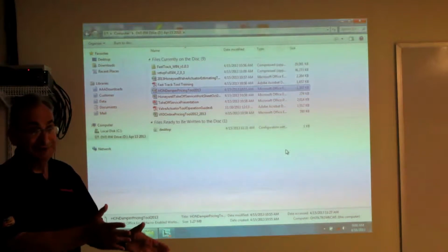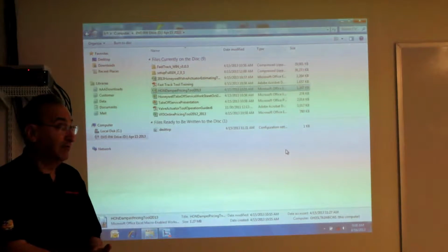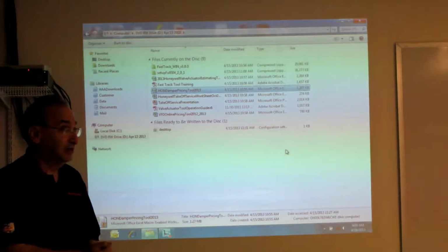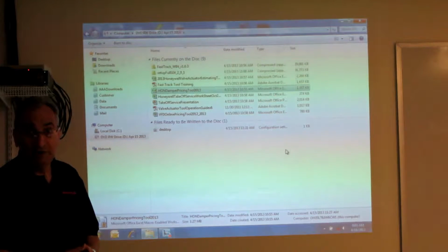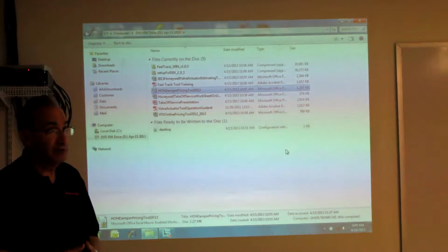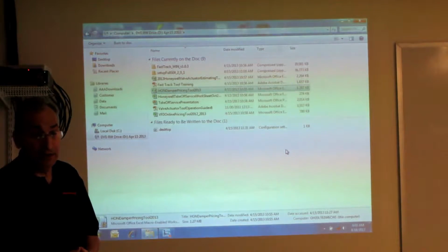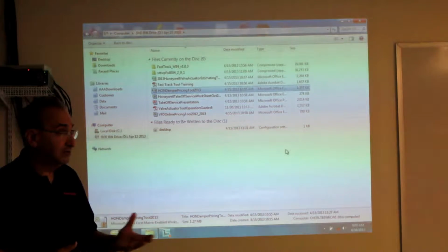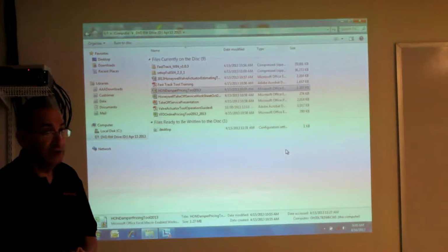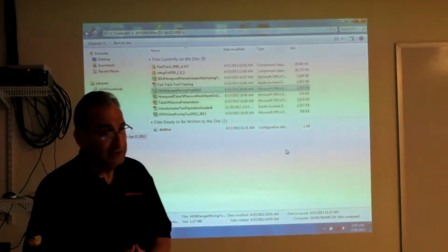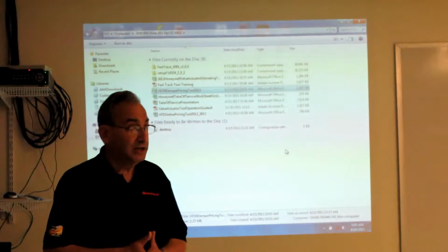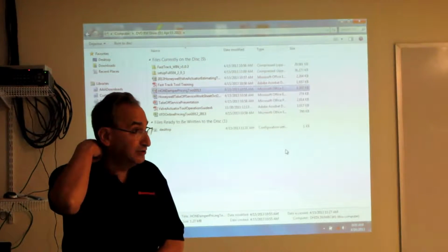That's right, economizer. It's required by code over 5 tons in some areas, some 7.5 tons. But on the larger systems, you should have economizers for fresh air and for cooling. Now we have some demos online for the Jade economizer and how to use it. Also how to calculate the energy savings with an economizer, which I didn't put in here, and I should have.